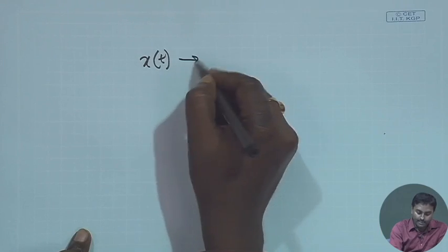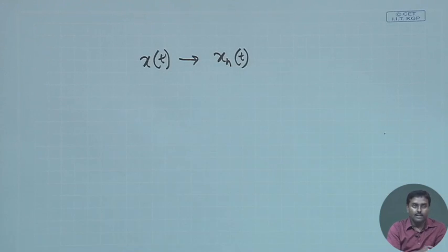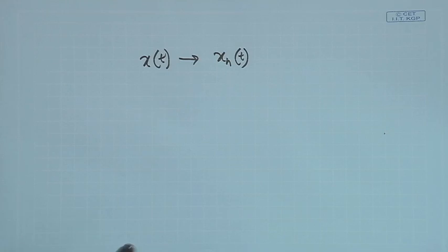Therefore, if you wish to employ a circuitry which does this transformation, all we have to understand is that to do this I have to take every frequency component and give a phase shift of pi by 2. The original delay element will not do that. You have to selectively take, maybe with a very narrow band pass filter, every frequency element, and for everybody you have to give a pi by 2 phase shifter. That is what you will have to do. Generally it is a difficult circuit to realize. There are techniques, but it is a difficult circuit to realize.